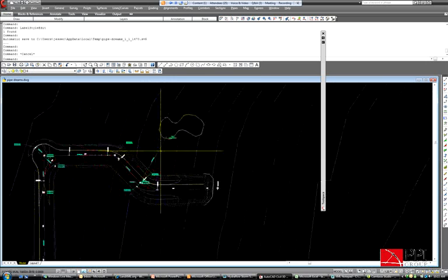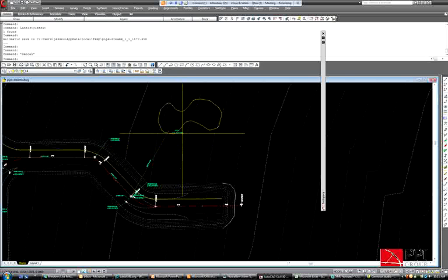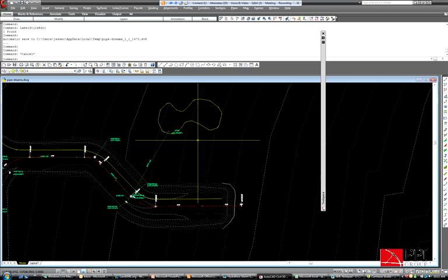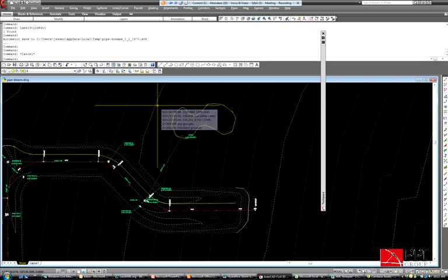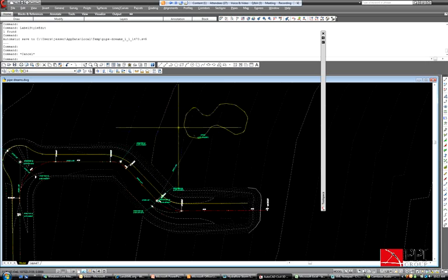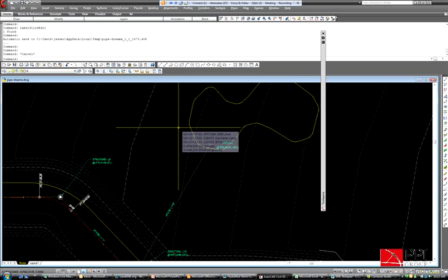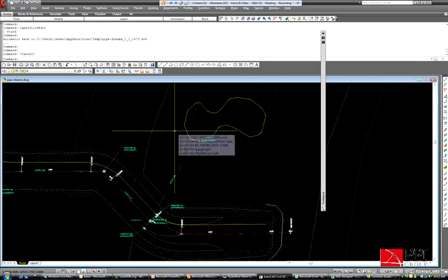So it runs up here and comes out to an outfall in this pond, which isn't built in this iteration of the finished grade, but that's my little peanut pond that we wanted to put in. Just an aside, I don't know if any of you had a chance to look at the new features. The reason we have this peanut pond in here is it shows off one of the great new features, which is in grading. I know it's not what we're talking about today, but grading objects are able to grade into each other. I'm not going to get into that, but this peanut pond is able to show that off. Then we come up to an outfall, 18-inch storm all the way along, and some catch basins.